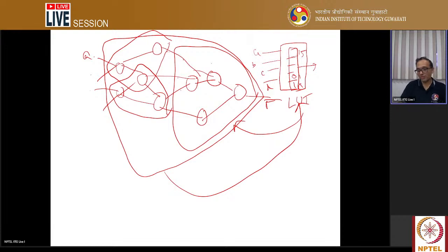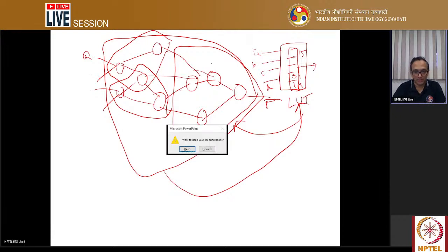So what I'm trying to show is that for the same design, you can have 1 LUT or 3 LUTs. So the point here is that it depends on how you implement this. You try to see how your design gets mapped into hardware, specifically for reconfiguring the FPGA. So ultimately it depends on how your tool is implemented.